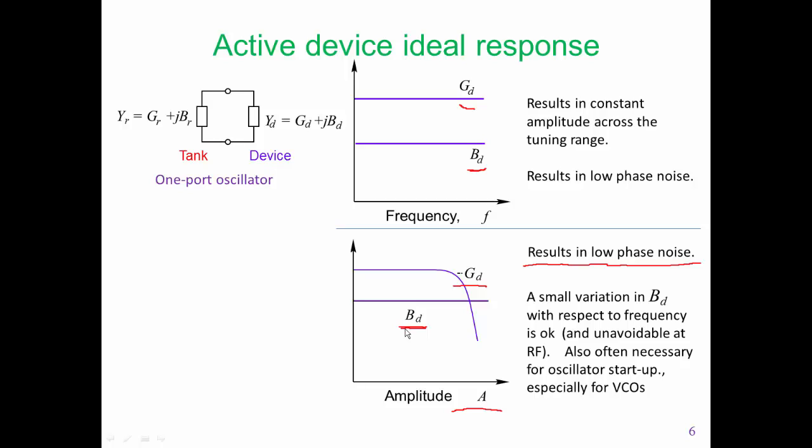If our amplitude variation, perhaps due to power supply noise, perhaps due to noise in the resistors in our circuit, can superimpose noise on our oscillation signal, that would change the frequency of oscillation. Now, of course, that is very small, but one of the things we're incredibly good at in microwave design is establishing the frequency of oscillation.